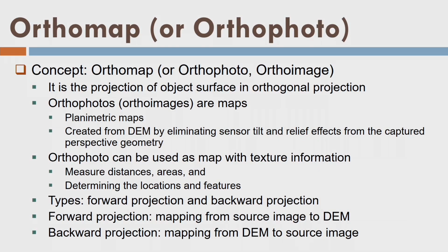The next product is OrthoMap. OrthoMap is generated from the DEM, and I already gave you one hint a couple of minutes before that I want to wrap image onto DEM, because DEM is just the raw value XYZ. It does not give me any other information. It is just a kind of terrain surface representation. But image gives its perfect texture value, and that gives me a real sense of the world.